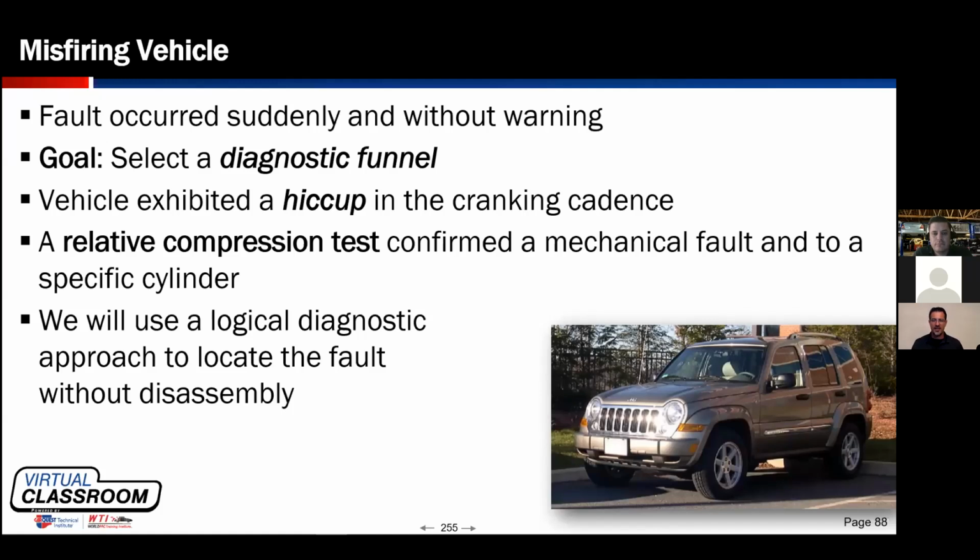I noticed cranking the engine that there was a disturbance in the cranking cadence. Notice I didn't say dead hole. This didn't make that same sound that Bryn said, that da-da-da-da, da-da-da-da. It didn't sound like the engine picked up speed. Actually, it kind of sounded like it did something different. It went da-da-da-da, da-da-da-da-da, like there was a pause. So I describe it as a hiccup. I don't know what else, but I do know it's mechanical in nature because I could hear it with my ears.